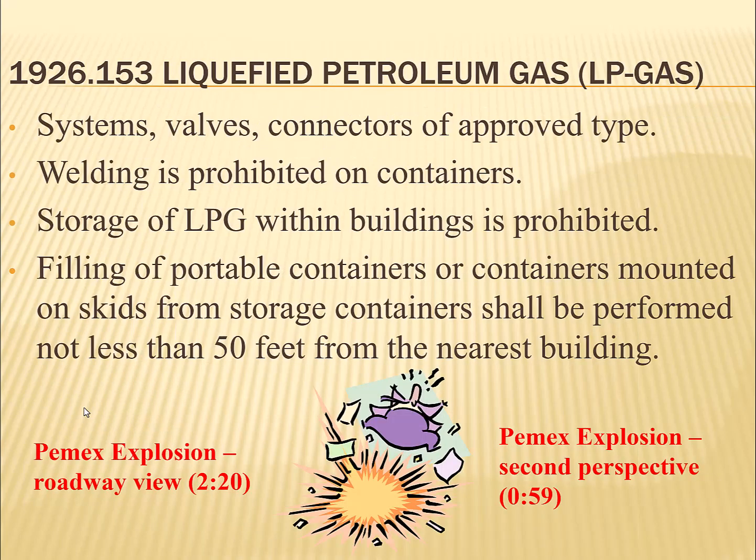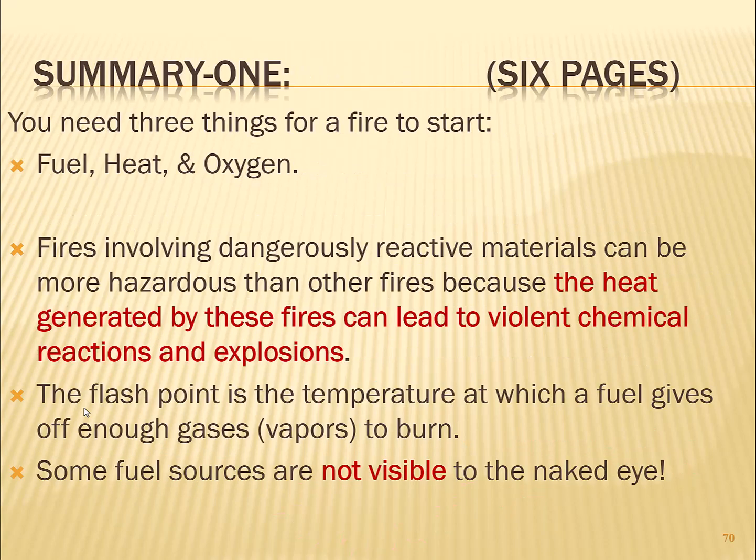Okay, beyond that, just mentioned the storage of natural gas, the storage of propane. You've got to make sure that you have gone to great efforts to separate them with distance, and make sure everything's grounded so you can reduce the explosive hazard there too.